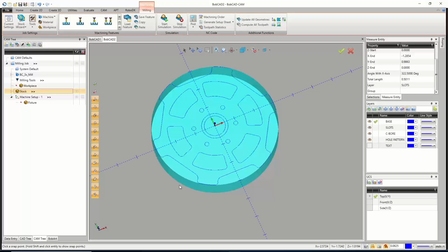Now we could do that, and I'll show you guys how to do it. So we then would go in and make sure we have the correct material for that part. And right now it's set to aluminum. This is just for feeds and speeds calculations, and there's a lot that factors into that. The entire tool library, which we're going to look at here in a minute, is set up as high-speed steel. I might as well just go into it.